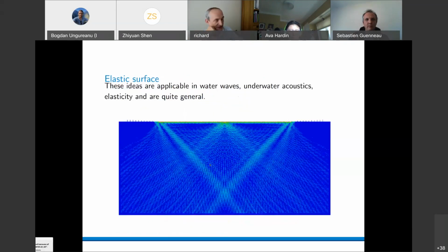So this is a simulation by Jacopo Maria De Ponti, who's a PhD student in Milan. So this is an elastic half space, and with a source on the surface, you get a Rayleigh wave, and the Rayleigh wave trundles along the surface. Here we've put an array, so an array of different heights of elastic beams or rods on the surface. And what we can do is, as we tune their heights, we can get this to apparently filter into compressional and shear waves going backwards and get a focal point.